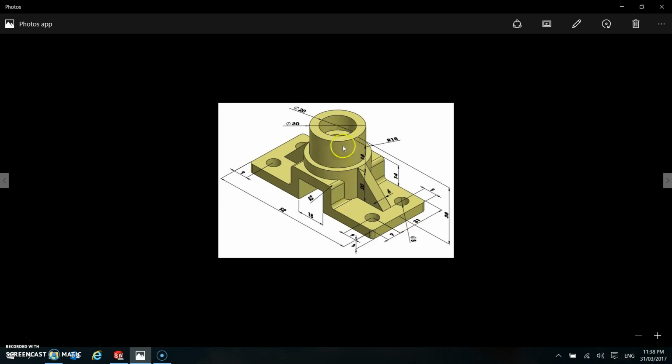And then I'll draw this second cylinder on top of the first one, project it up. I'll then draw on the side plane, the front plane, these side brackets. Rotate it around to the top plane again and then put these holes in. Okay, so that's my intention.